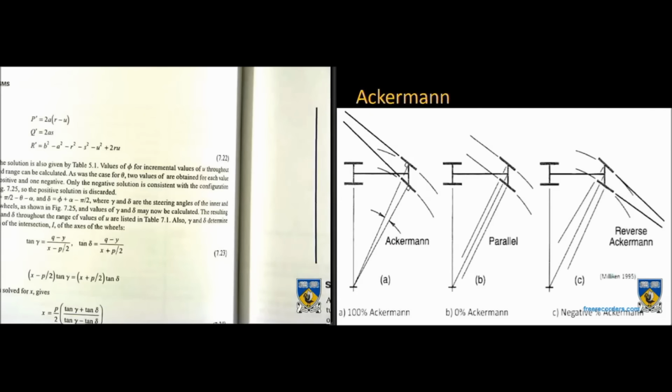You see this a lot in Formula 1 and other cars which have really high lateral load transfer. As you push down on the outside wheel, it gets heavier, and it also wants a high slip angle to generate the high force. As such, reverse Ackerman is used on those cars to maintain that situation and get the maximum grip out of both wheels.